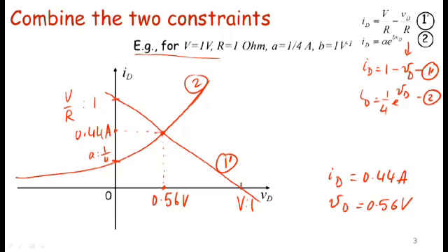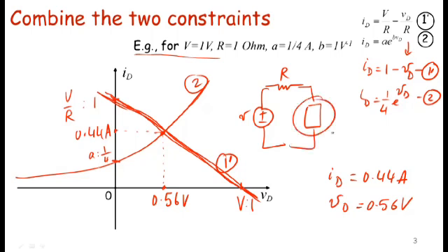Before I jump to one other thing, let me define something for you. Notice this line here. This is a straight line that reflects the Thevenin constraint that I apply on my nonlinear device. I mentioned earlier, we're going to do this again and again. I think you will see this at least 10 more times in this course, where I take a Thevenin equivalent of some voltage V and some R, and apply that in series across something interesting.